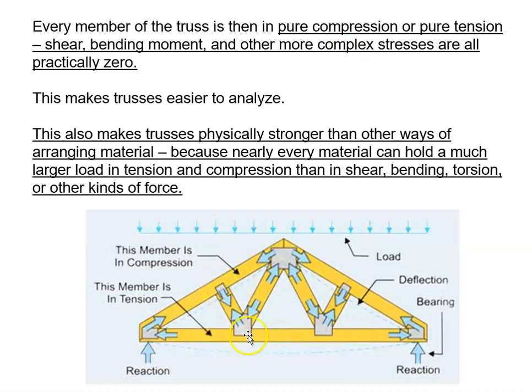Okay, so all these interior pieces are either, and that's what we see, these arrows. This one would be in compression, being pushed on. This web would be in tension, being pulled on. The top chords are in compression, two arrows facing each other. The bottom chord is in tension, two arrows opposing each other, facing in opposite directions. And then you see a little dashed line there that kind of shows a bending, kind of similar to the beam. And this is, of course, showing that we have a uniform load being applied to the top, snow, for example. Okay.